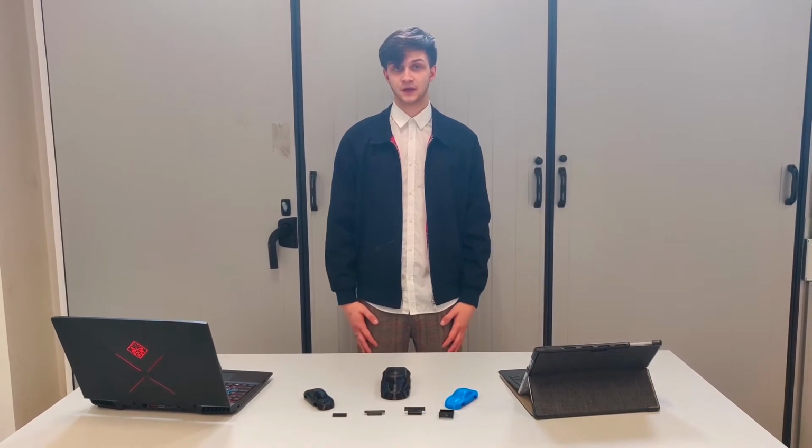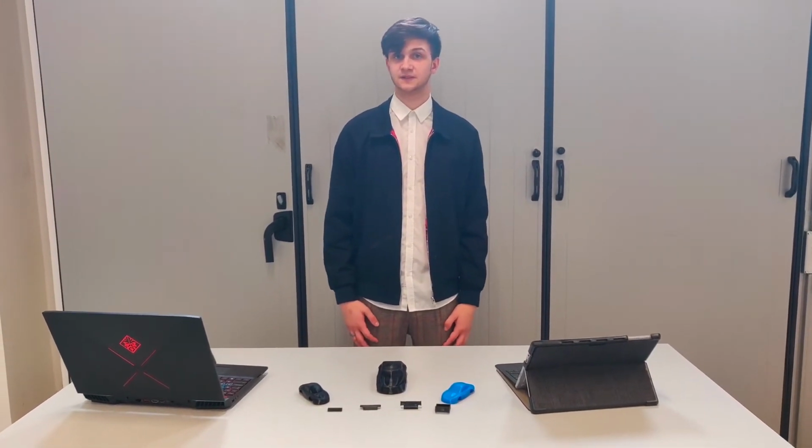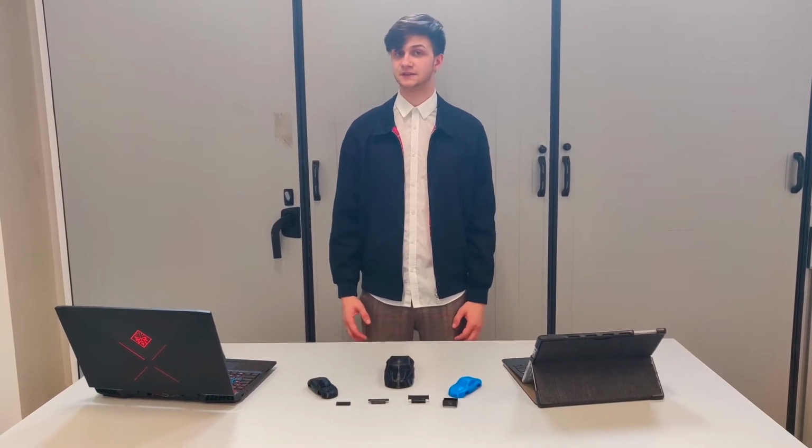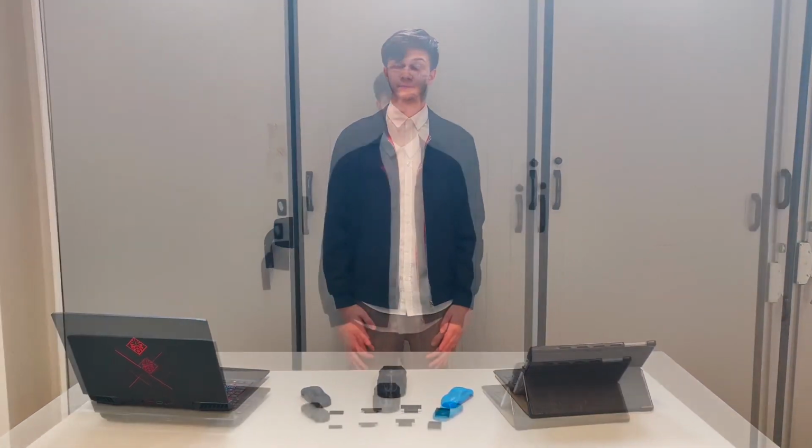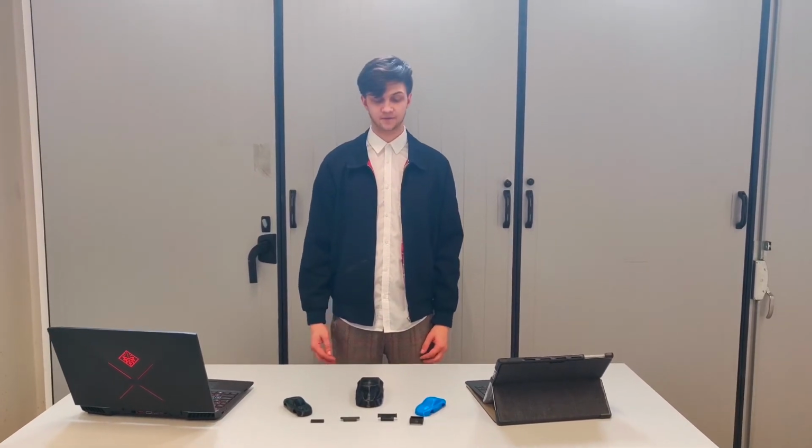The rear of the car was mounted to the wind tunnel's balance, with drag and downforce being measured. Wind speed was increased at 5 meters per second increments, starting at 15 and going up to 30 meters per second. Each set of results was recorded. The experiment was repeated 3 times for each spoiler, and then an average was taken to get an accurate reading.